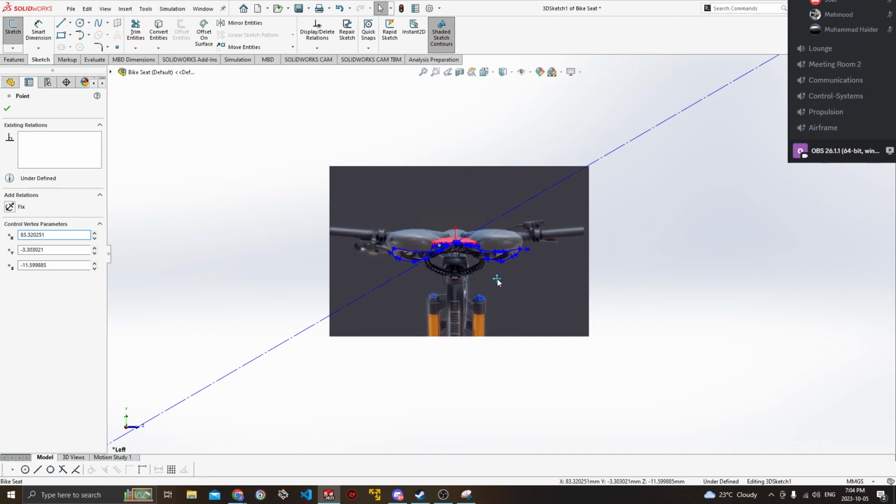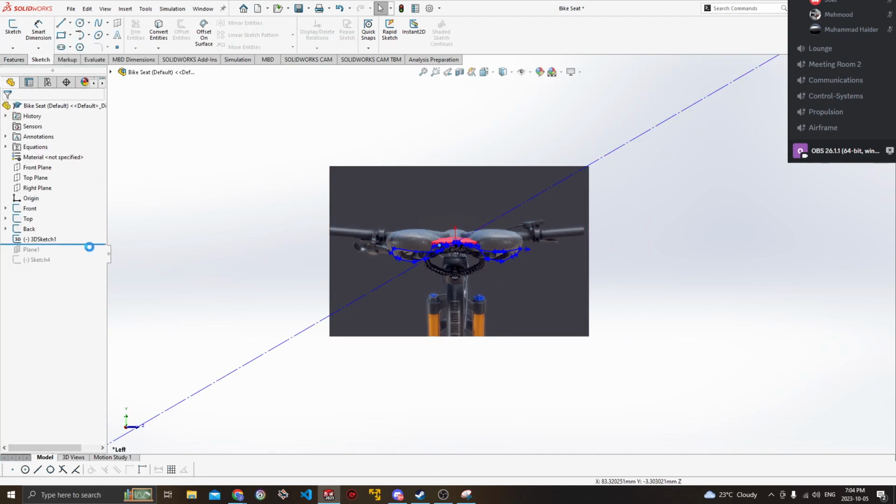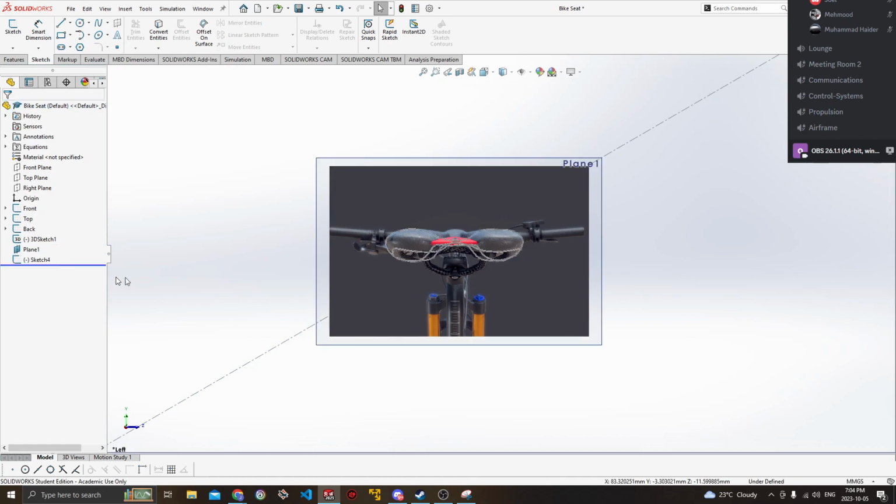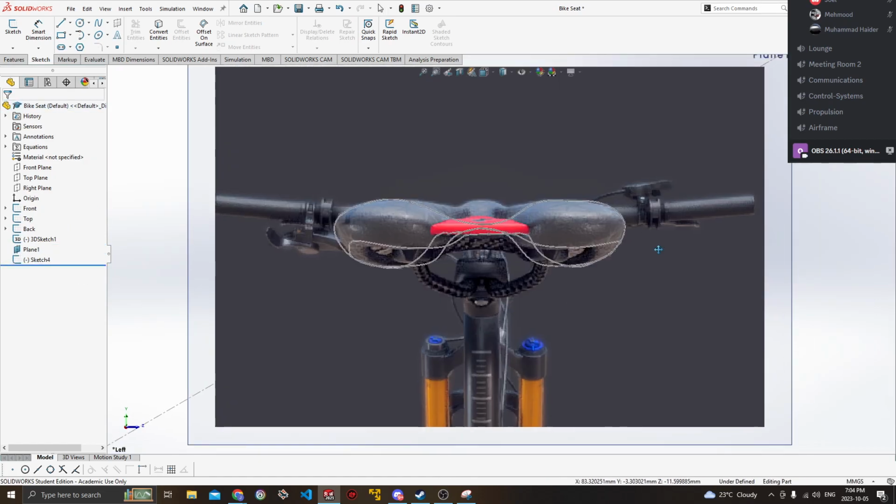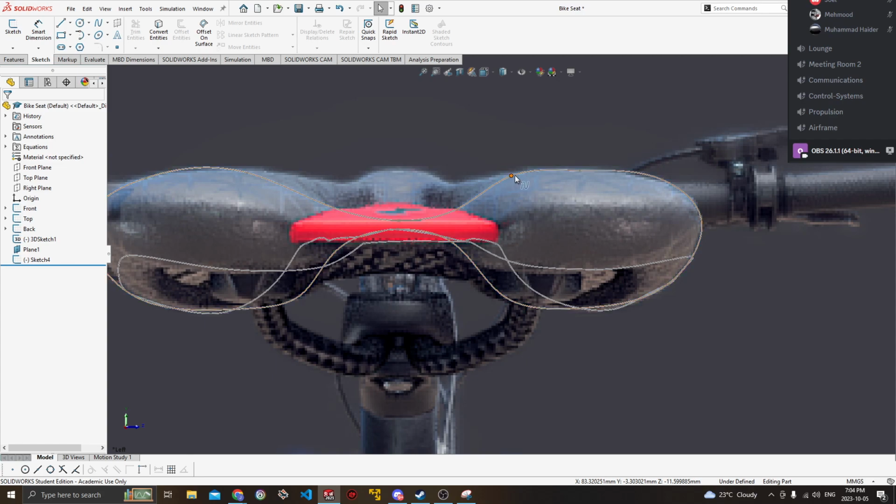Okay, that's going to bother me forever, but that's fine. So we're going to exit the sketch again. If we pull this back down, what it should do, which we can see, is that it's now edited this sketch that we created. And just like the equations that we made before, it has propagated the changes that we made in this sketch through to the sketch that we've made.